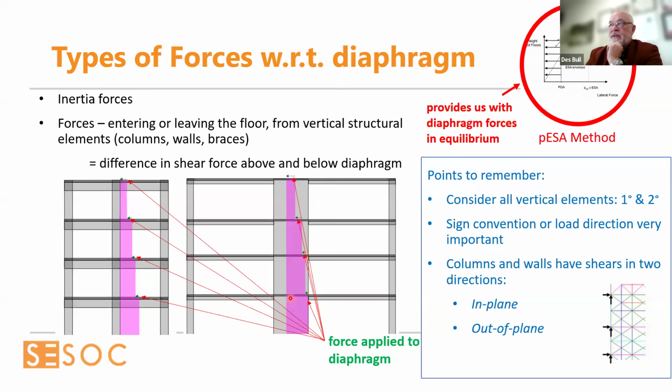The other thing to remember is, when you do this modeling, a lot of the conversation around modeling is that every column and wall has actions that are going in and out of plane for that column or wall. A lot of people forget to put the out of plane forces in their model and wonder why it doesn't work.